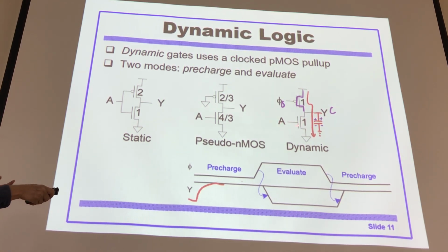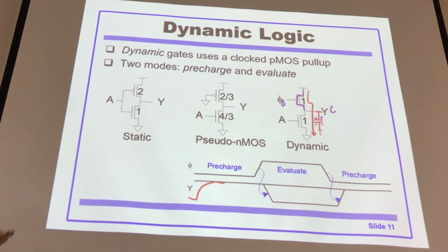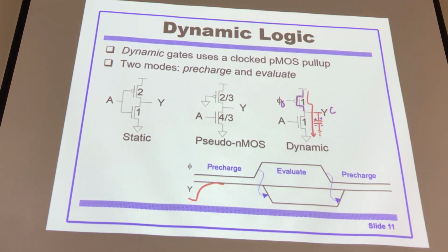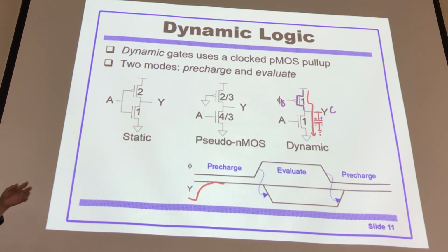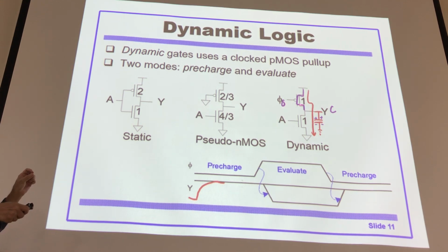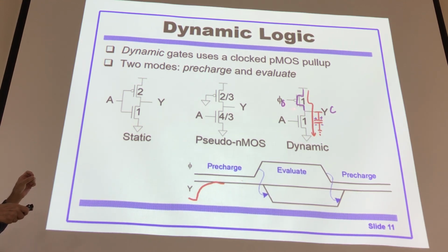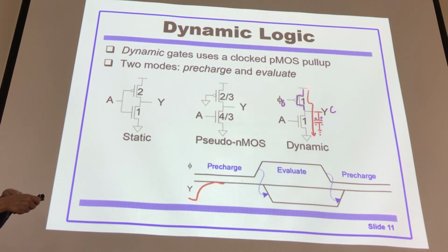Assume that the NMOS transistor is off. Simply assume that it's off during the pre-charge phase. We are doing that again. During the pre-charge phase, clock signal is low, so PMOS transistor is on. Just assume that this is off, okay? So there's a current from VDD to the ground. The current goes through in a path.